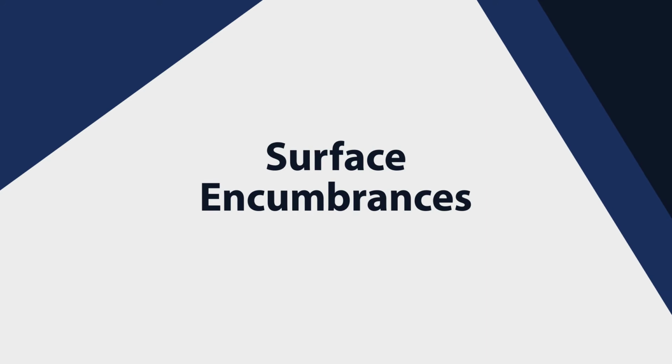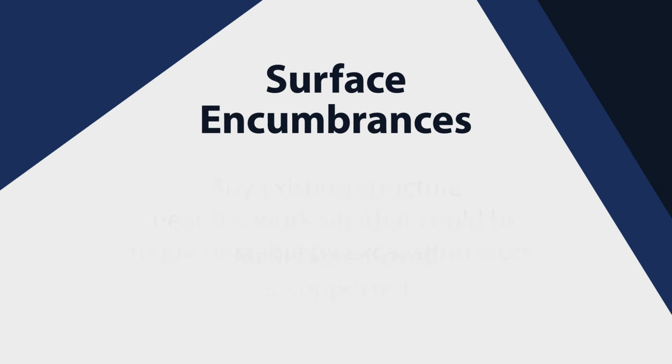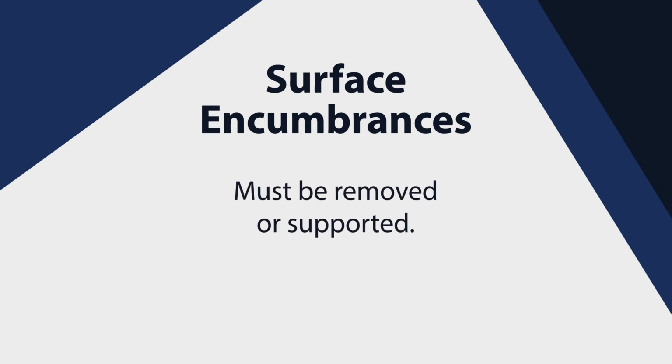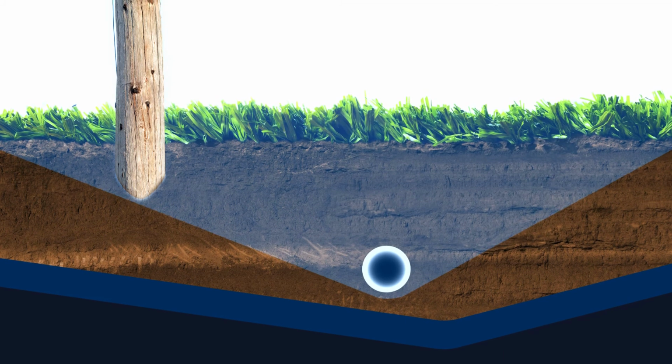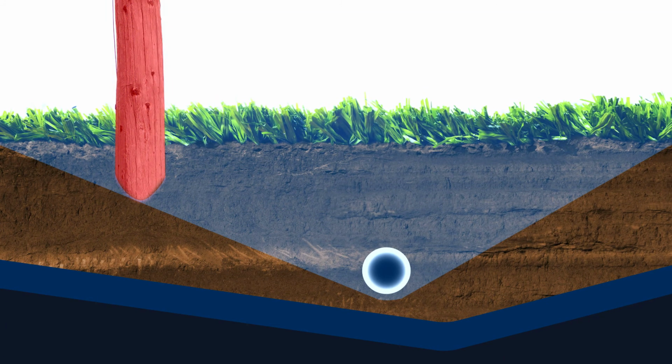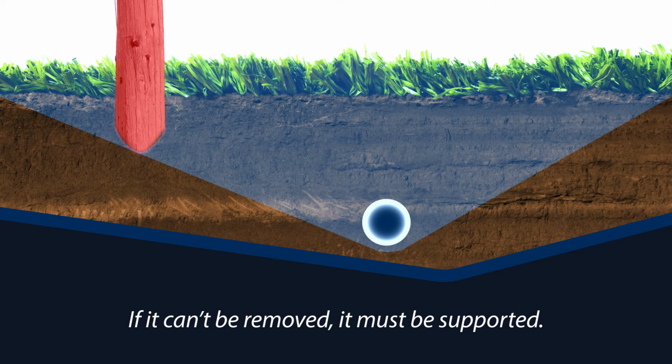When starting an excavation on a job site, the first portion of work is dedicated to protecting the site. First, look for surface encumbrances or any existing structure near the work site that could be made unstable by excavation work. All surface encumbrances must be removed or supported before excavating to protect employee safety. For example, a power pole that may be undermined during the excavation should be removed prior to starting the work. If it can't be removed, it must be supported to prevent collapse once the work begins.